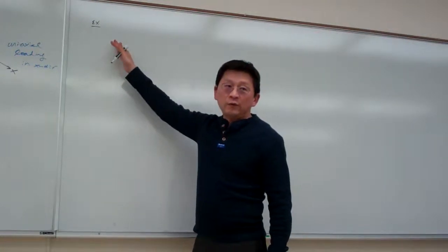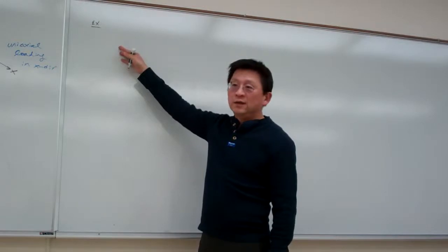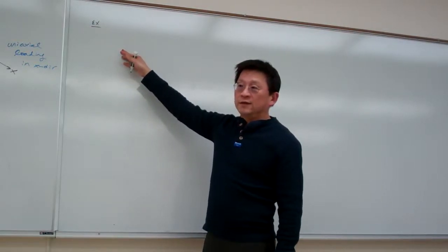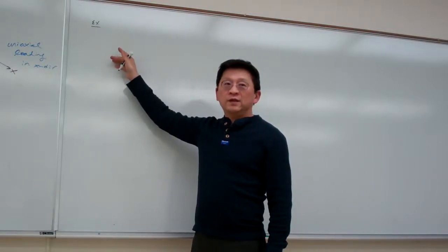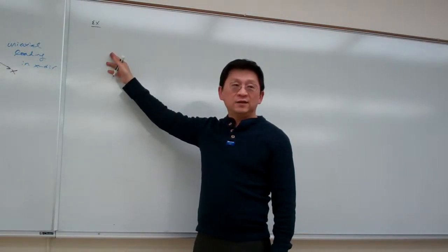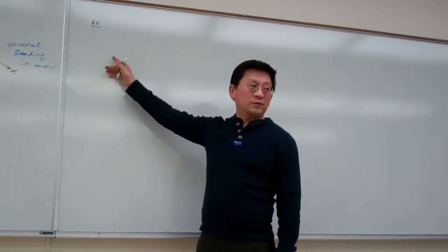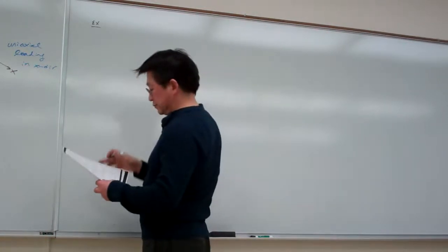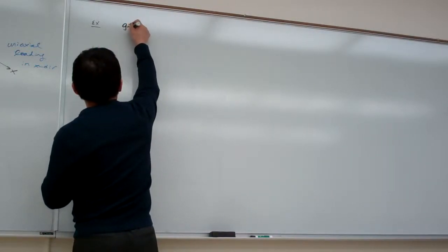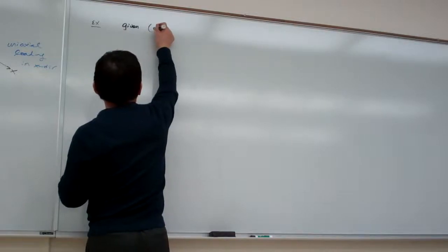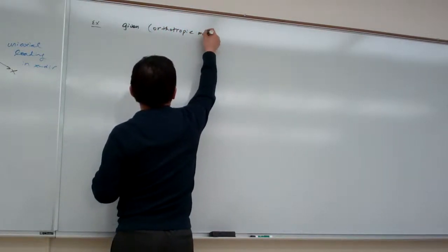This example I want to use for a two-dimensional orthotropic material, to show that the principal directions of stress are not in the same directions as the principal strength for an orthotropic material. Okay, so here we try the given orthotropic material,